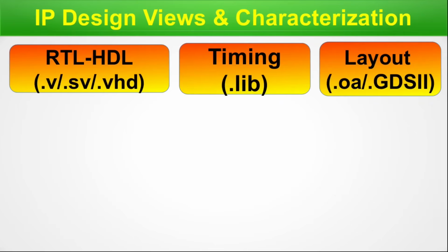Here, at the unit cell level, you design everything in the form of diffusion layer, poly, substrate, metal 1, via 1, metal 2, etc. The formats that you deal with are .OA and GDS2. For this, you use tools such as Virtuoso or Custom Compiler from the major EDA tool vendors. So, you must develop your skills on these tools. One free tool you may use to practice the basics is Magic Layout.